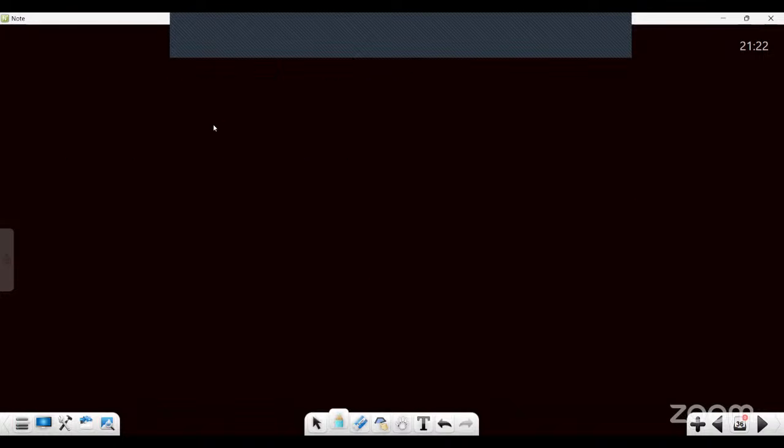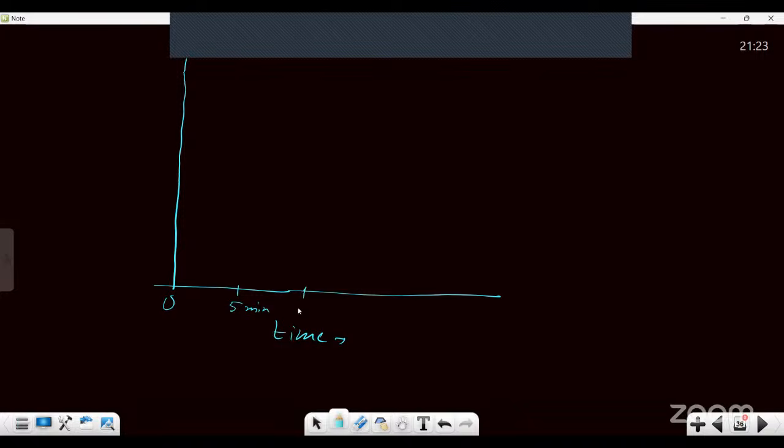Now, I will talk about the melt composition and how, with time, the impurities are removed. This graph is very important; if you can, try to remember it. This is the time of blowing in the LD converter. This is 0, this is, suppose, 5 minutes of blowing, this is 10 minutes of blowing, where blowing means I am blowing oxygen, 15 minutes, and this is 20 minutes.